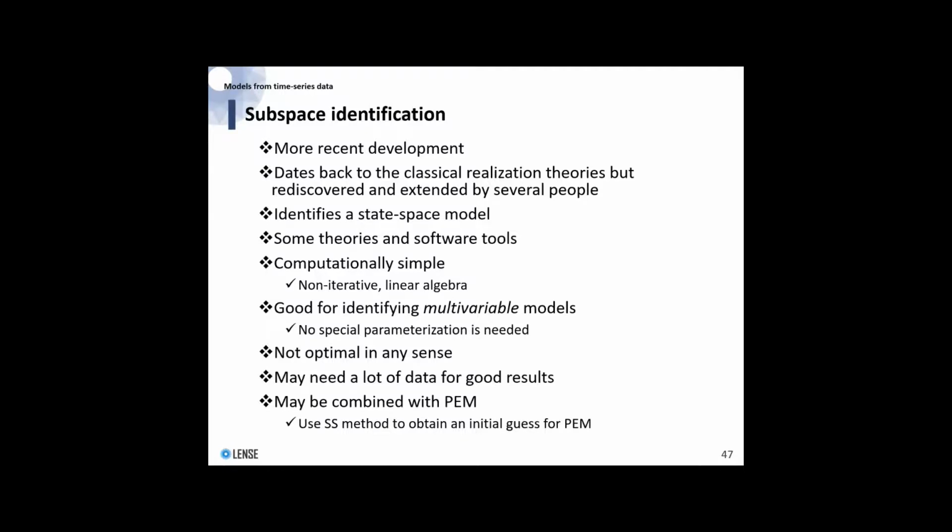What that means is that I cannot use y2 to estimate y1, which is what you would need for inferential type applications, soft sensors, for example. So really, you need a multiple output model in order to capture correlation among different outputs to make the model really useful.